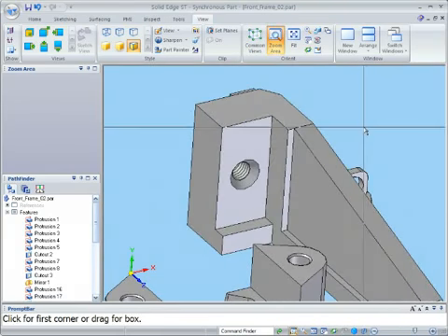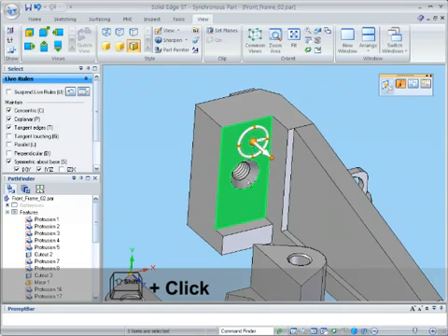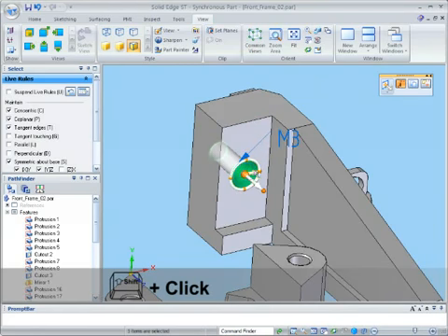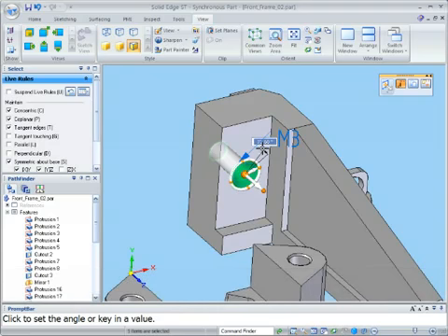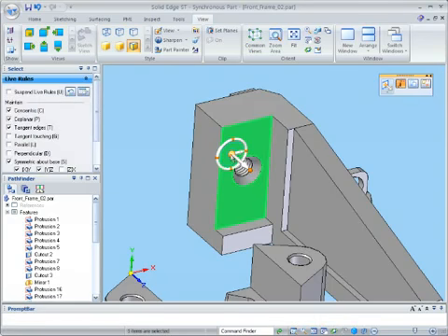To accurately rotate the steering wheel around its axis, shift-clicking on the torus allows it to rotate. Using the tab key moves focus to the dimension box, allowing you to key in a precise angle. Mouse position can also be used to infer the opposite angle if you want. Now with the steering wheel rotated to the required angle, you can use it to make your intended modifications.